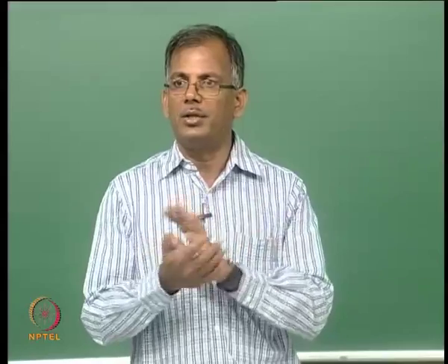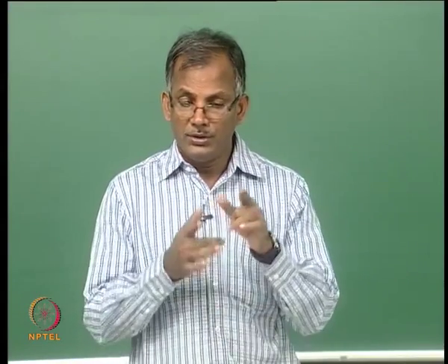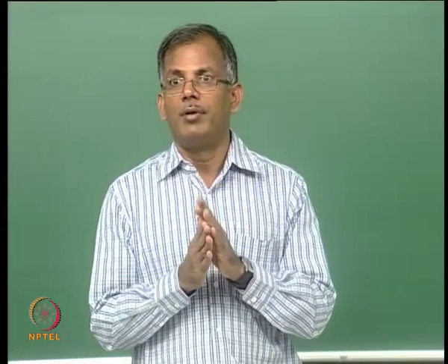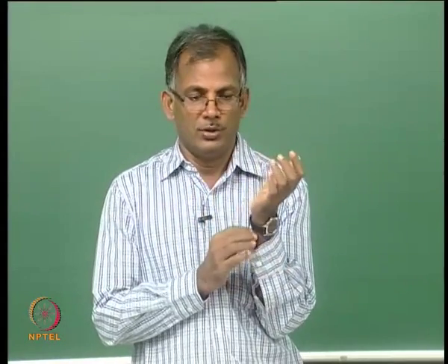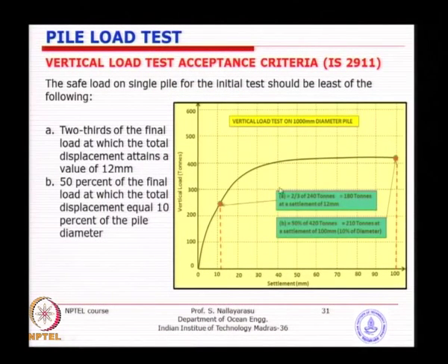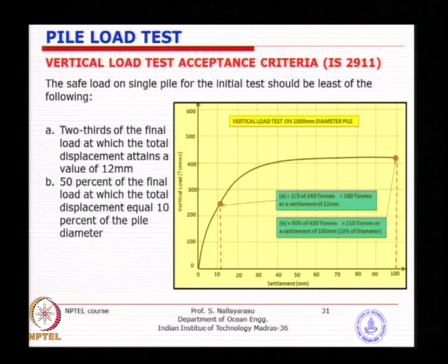So, that is the criteria that you are going to apply, and of course, this is written on the basis of onshore structures. 2911 is a code for bored concrete piles for onshore applications, not even for coastal applications. That is why you cannot blindly apply this principle to a coastal structure or to an offshore structure, where displacement criteria are different from the onshore structures.